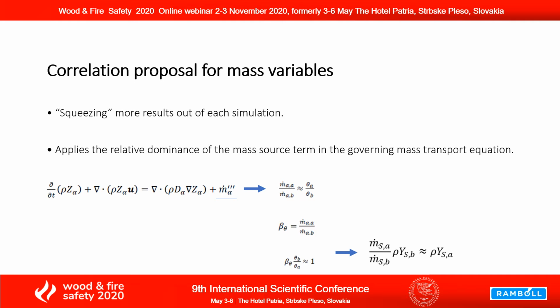This issue of computational cost and uncertainty is addressed in the study by proposing simple formulas for correlating FDS input to its output. Often, output of interest is related to some mass quantity, such as the soot densities, which are relevant for computing visibility distances through smoke in egress routes. Further, the soot densities in egress routes are highly affected by what fuel happens to be chosen to combust in the simulation, whether it be wooden furniture or plastic commodities.